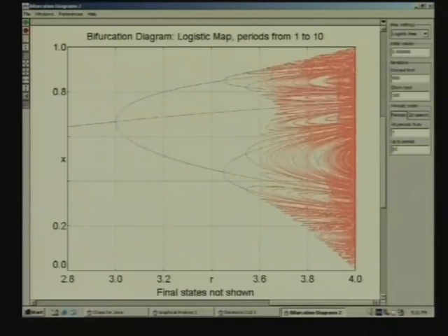Yeah, I said that there is a lot of flexibility in the sense that suppose a system is a linear system. A linear system means its behavior is exactly given by the eigenvalues and that is it, you can do nothing about it. If you want to do something, change the eigenvalues. That is how the whole of control theory works. You put some feedback, and that feedback essentially changes the whole system's eigenvalues, and that is how it works.